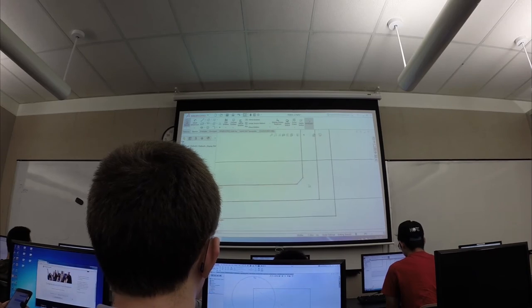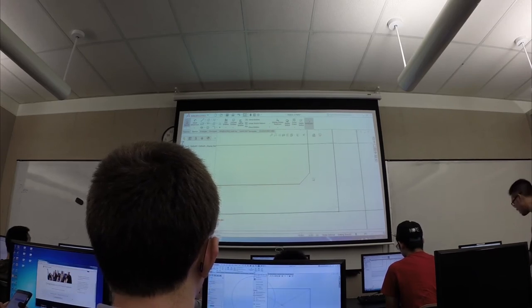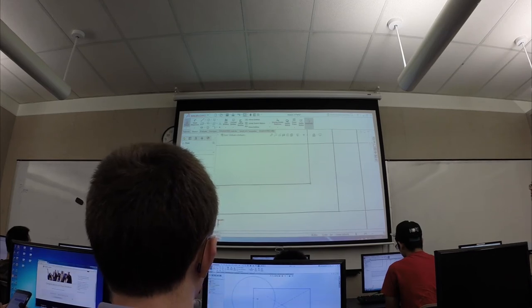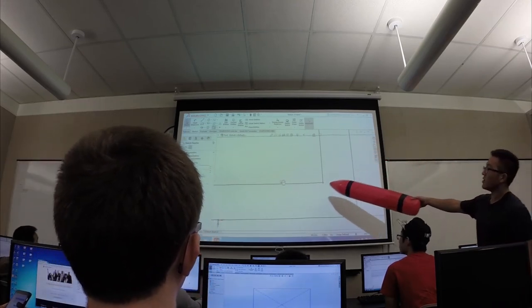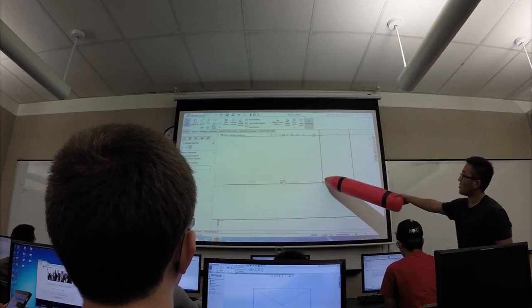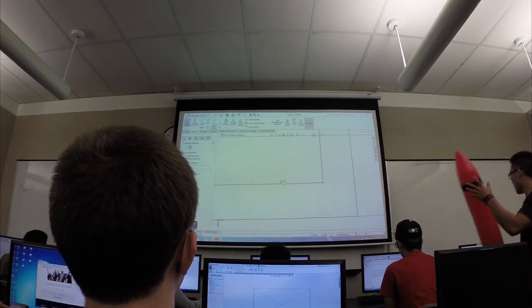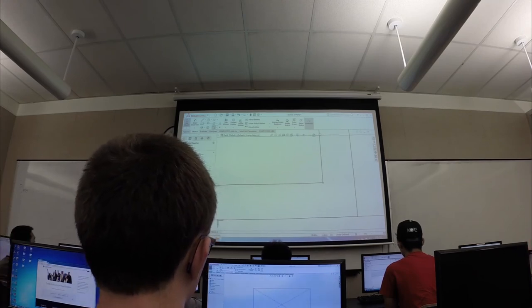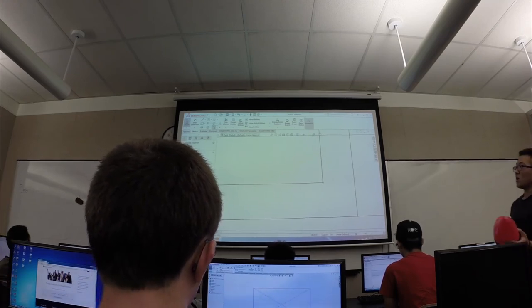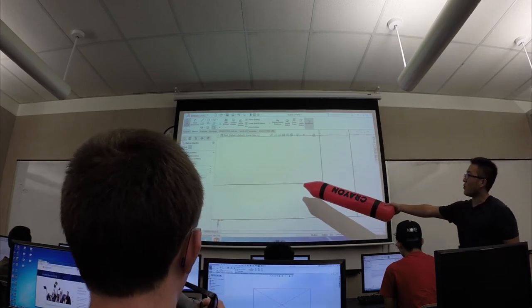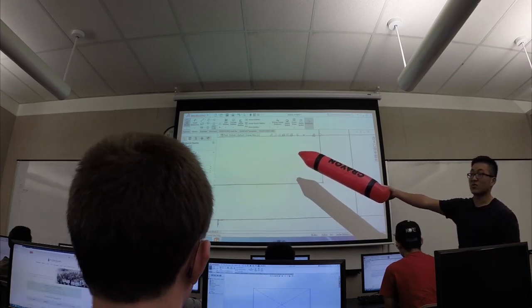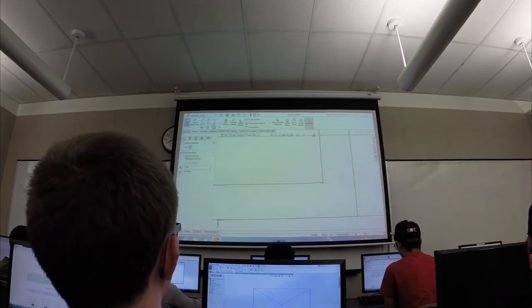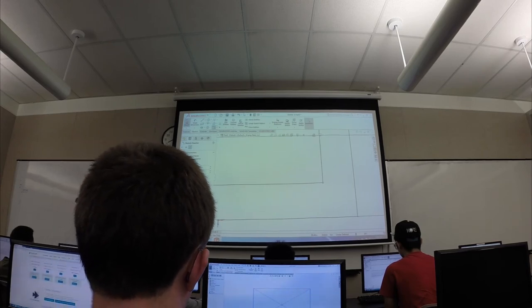Whoop, the plan didn't work. There we go. So now it's returning what the values say, right? You have 2 inches offset from here, but you only have a 1 inch offset from there. You could also define it as an angle and a distance. So it says, okay, I want this to be this length, and I want it to be at a certain angle, right? So instead of a distance relation, you could do an angle and length relation.